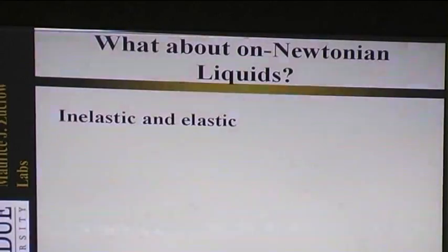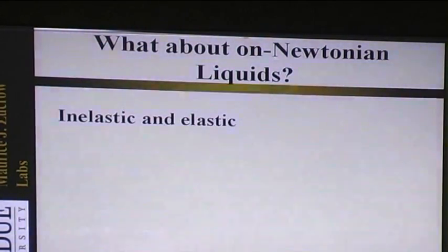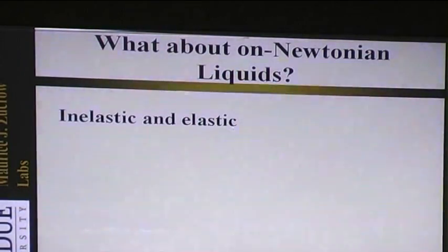So everything I've talked about so far is basically for Newtonian liquids, classical things like aviation fuels or IC engine fuels or water-based substances and so on. But one unanswered issue, at least up to a few years ago, was how the secondary breakup process changes for non-Newtonian liquids. That slide says non-Newtonian, but it obviously should say non-Newtonian.